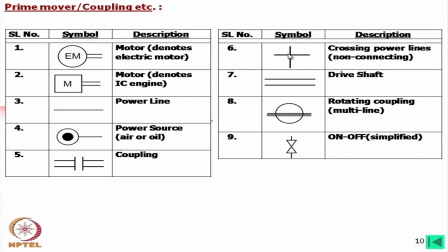If you would like to show a junction point connection, what you have to do is move one of the lines slightly to the right side or left side and show the connection. That means this is a junction point, otherwise this is a crossing line. The best way is that you can cross like this or you can cross like this.